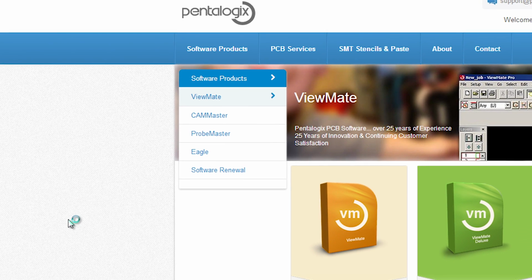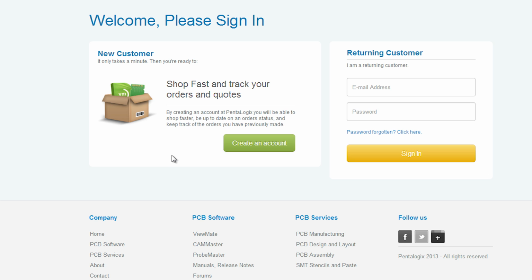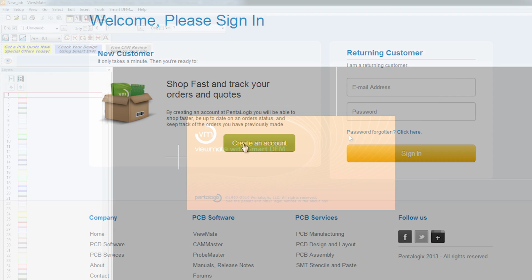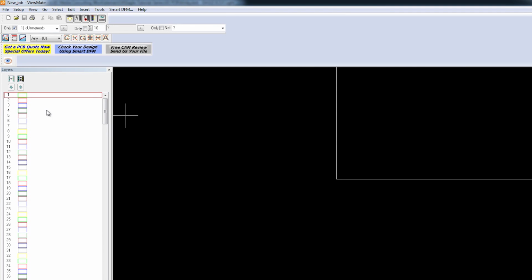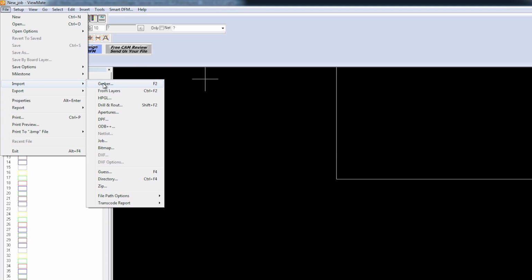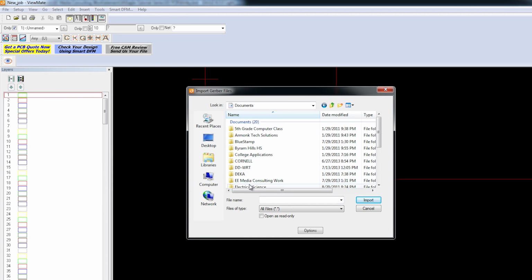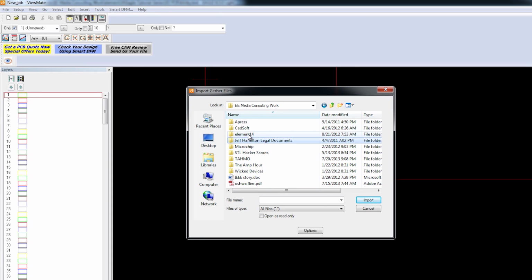There's a link to download in the description of this video. Make sure you just get the free version. You don't need anything complicated. Of course, it's going to do that annoying thing where you have to make an account, so go ahead and do that before you can download it. Once you've finished the extremely annoying install process for ViewMate, go ahead and open it up. Go to File, Import, Gerber, and let's go grab the Gerber files that we just generated.